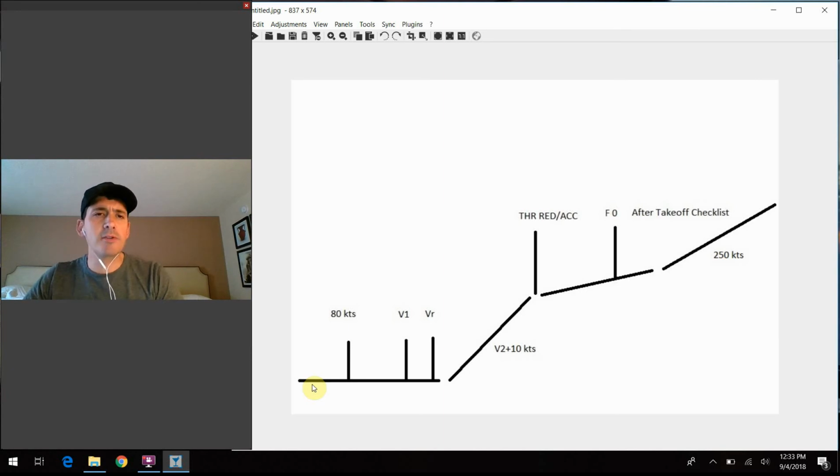And kind of an interesting little sidebar, you're starting to hear more and more about these geared turbofan engines, where there is actually a gearing system and a gearbox that takes out of the equation this business about the water wheel and the acceleration time lag. But that's a whole other kind of future technology. And most of the engines still out there on our transport airplanes these days are still the high bypass turbofan with the setup that I'm talking about there.